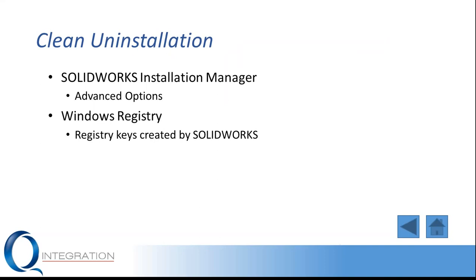So how can we perform a clean uninstall? Well, the SolidWorks Installation Manager makes this very, very easy for us. If I go through and do an uninstall, you will notice that there is an advanced set of options down at the bottom.